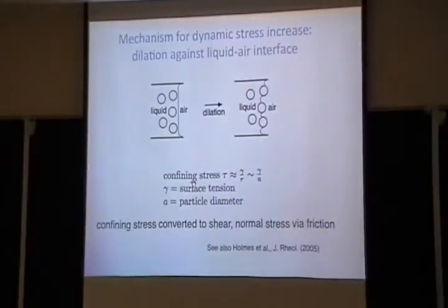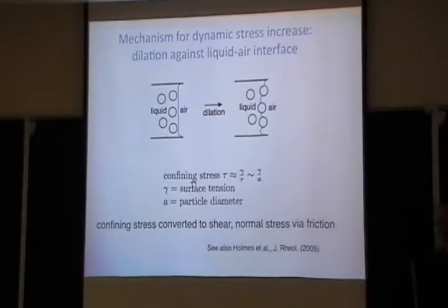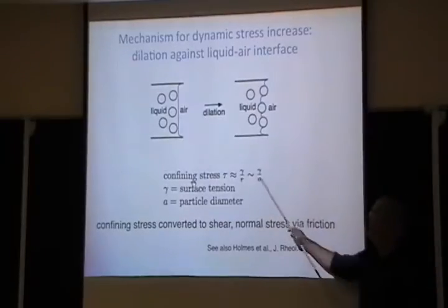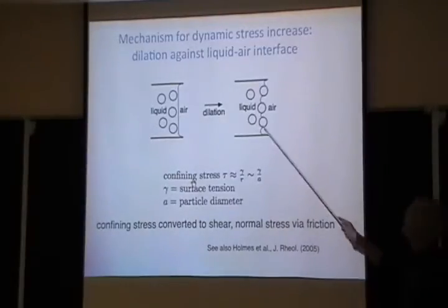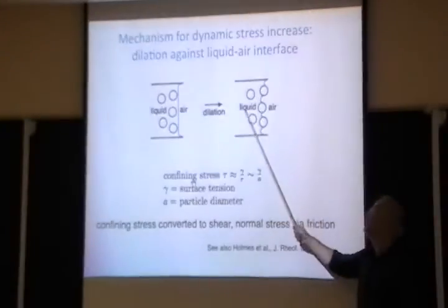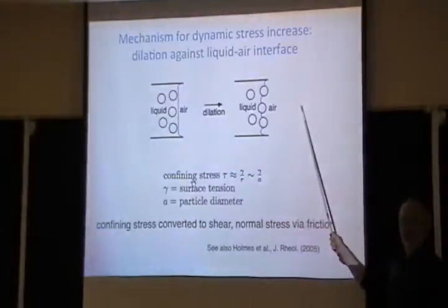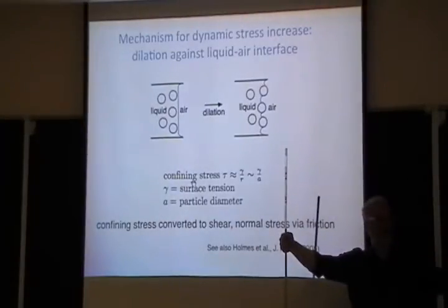So this gives us an idea that once you shear, you can use menisci. All right? They set a stress now. And the confining stress is exactly what we talked about before, with some prefactor that depends on wetting and whatnot. All right? And so now what we say is that when you shear so much here that your dilation wants to push this out, that it overcomes that confining stress, well then you can't have shear thickening anymore, right?